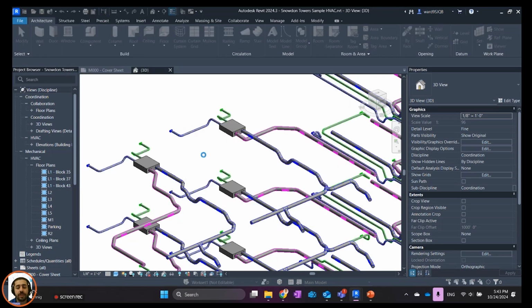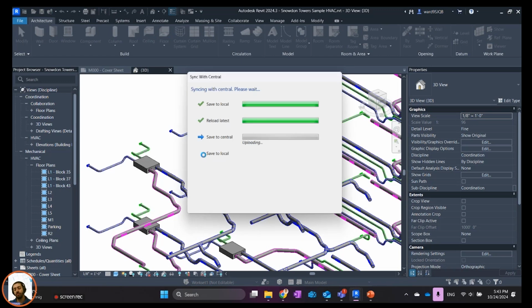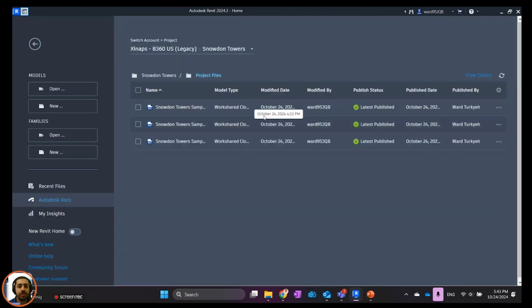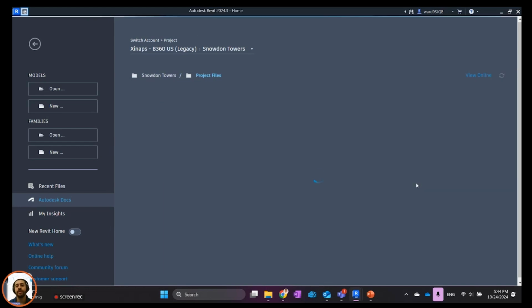Click on OK, because now Revit is collaborated on BIM 360 and BIM 360 is connected to Verified. So as soon as I make an update on the Revit file, an update will happen on BIM 360, but I just need to push it from here. I will go to my collaborated files. You can see that I've already done 3. So all of them have the latest updates, but I just deleted an element and I synced the model. So I just need to refresh.